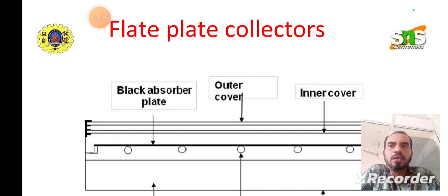Then it differs based on the mounting. A collector can be mounted to remain stationary, be adjustable as to tilt angle, which is measured from the horizontal, to follow the change in solar declination, or be designed to track the sun. Tracking is done by employing either an equatorial mounting or an azimuth mounting for the purpose of increasing the absorption of the daily solar radiation.